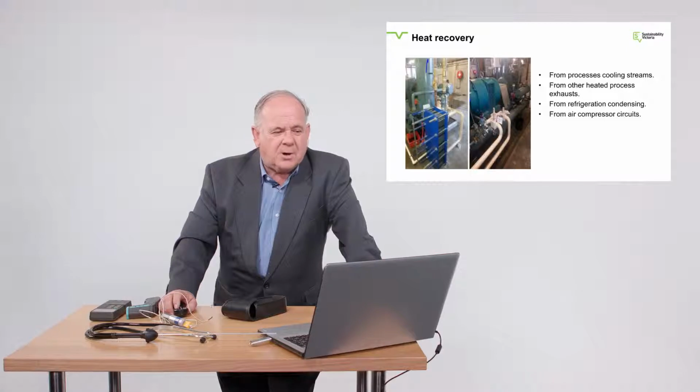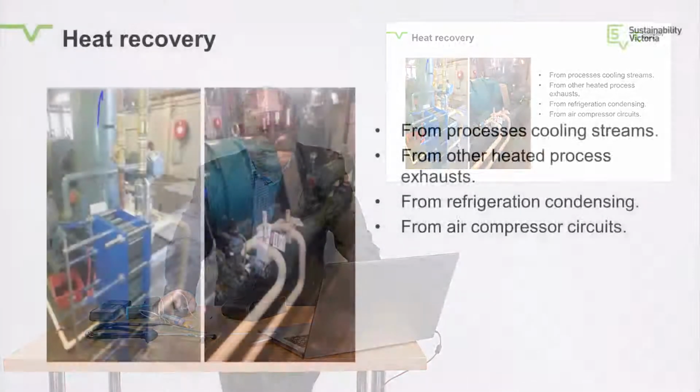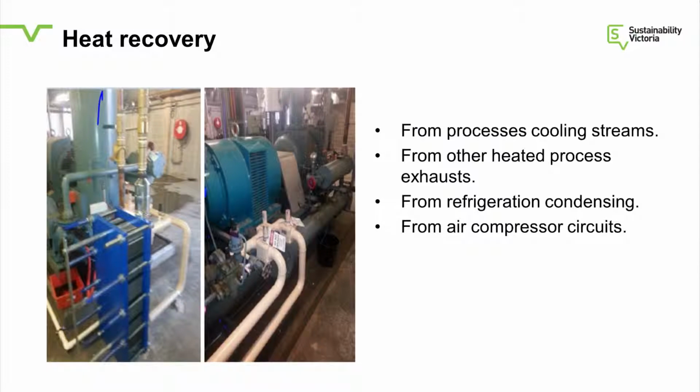Okay, heat recovery. Michael might have spoken a little bit about this on the refrigeration side, but one area that we've seen a move is to recover heat from refrigeration plants in lieu of gas. So in other words, most larger factories have screw-type ammonia compressors these days where you can take the heat from the oil coolers on these units, or you can take the superheat from the condenser circuits to replace natural gas for preheating. One plant we did, we got about 50 degrees C out of the oil coolers for washdown preheat, and about 55 to 60 degrees out of the condenser.